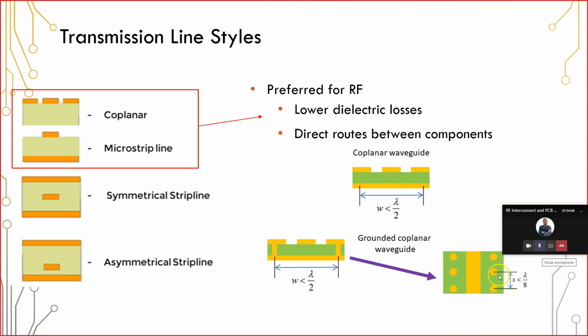Or, in making these vias closer spaced together, you can actually add another row but stagger it. So you'd have a via right here and then a via right here, and so on down the length of this. That's another way that you could try to pack more vias into this smaller space, and then ensure that you still get the required level of shielding and isolation for the electromagnetic field inside of this structure.